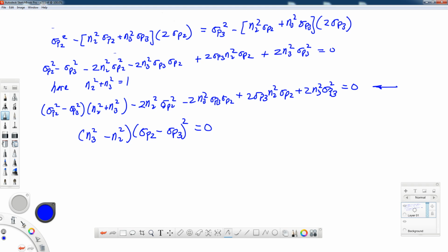If you think about Mohr circle, we'll talk about Mohr circle soon, but if you're taking this class, chances are you've had a class in mechanics of materials. If you think about a class in mechanics of materials where the in-plane normal stresses are equal, you have an equal biaxial stress state, Mohr circle is a point and you don't have any shearing stresses develop. So that is kind of a derivative solution where we don't have any shear stress.